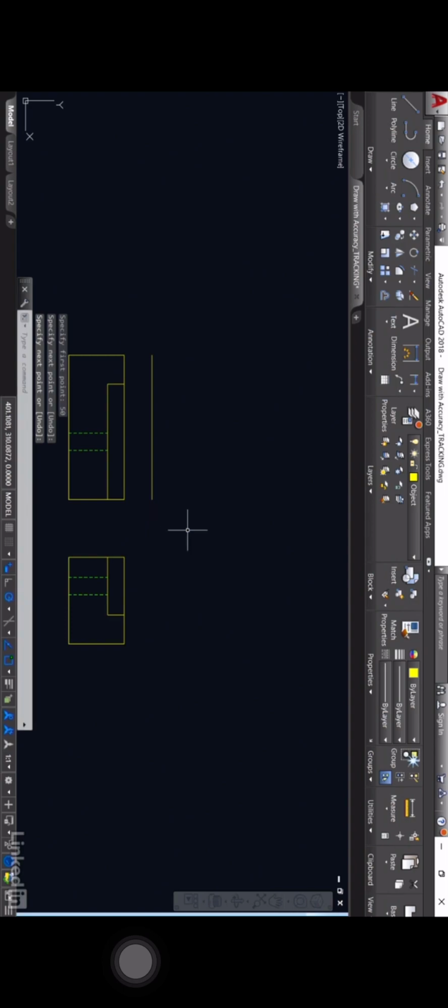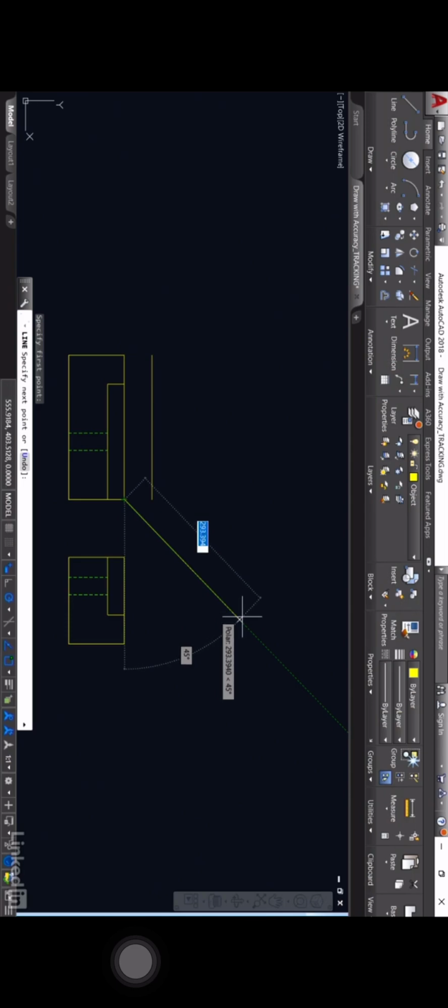So how do I know the depth of this shape here? How do I get that to project over here so I know how high it is? Well, I can draw a line and use it as a sort of sacrificial line, and I can go from this corner here and drag it up this way. Make sure you get your 45-degree polar tracking, like so. I'll click once, but make sure it goes all the way past the end of that right-handmost view there, and click, and then enter to finish.